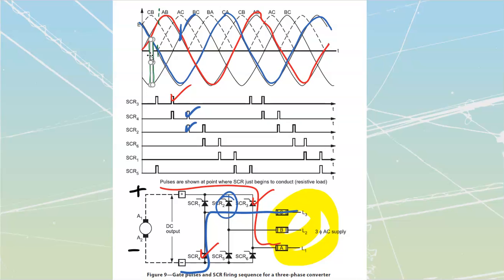Oh, beautiful. If you take a look at that green line over there, that's going to be my magnitude of voltage. And you can see how this thing stays the same magnitude of voltage, because it's just switching line to line as it goes across, up and down, up and down, up and down like that. It's a pretty cool thing. All we're doing is just switching from component to component. We're monitoring what's the top line, what's the bottom line, and then triggering these SCRs at the same time. Okay.